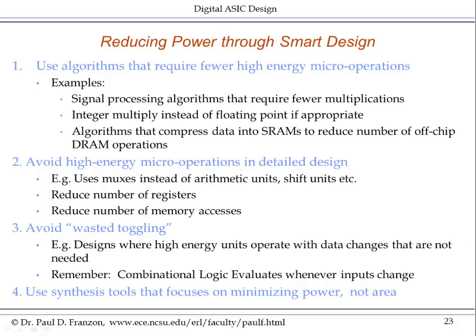So this brings me to reducing power through smart design. In the first module, we talked about clock gating and dynamic voltage and frequency scaling. These are all system level ways to reduce power in certain scenarios that are not necessarily available to the RTL designer. They're often done at the system level. Major blocks have their voltage turned down, or major blocks have their clocks gated. The logic designer can't influence it a lot.